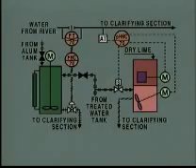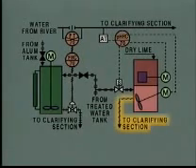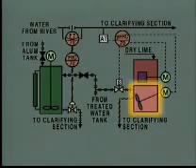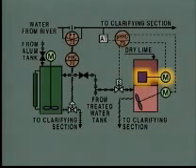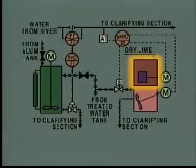This P&ID shows the components of the chemical mixing section. This symbol represents the hose to the flash mixer in the clarifying section. The lime solution carried by the hose is made in the mix tank of the lime system, so the tank and its motor-driven mixer could be checked for visible problems. Lime is added to the mix tank by this motor-driven shaker, so the shaker could be checked to see if it's clogged or damaged. The motor could also be checked for problems. Lime for the shaker comes from a hopper that's filled manually, so another thing to check is whether the hopper contains a supply of lime.